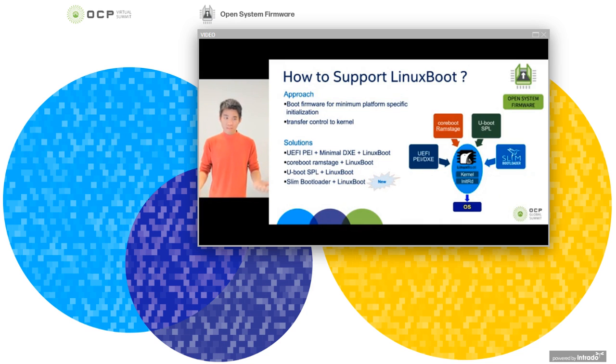And in the market, there are already mature solutions for UEFI, coreboot, and also U-Boot payload. So here today we are introducing a new support model, which is using Slim Bootloader together with LinuxBoot. The concept is also straightforward. Let the Slim Bootloader do the platform-specific initialization, integrating the FSP binaries and doing the FSP-specific functions. And after that, we just pass the control to LinuxBoot.